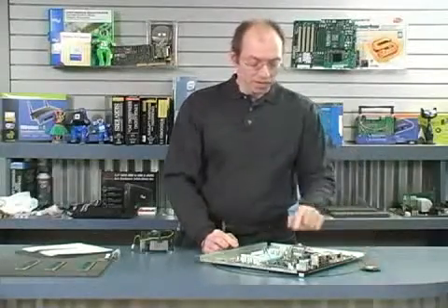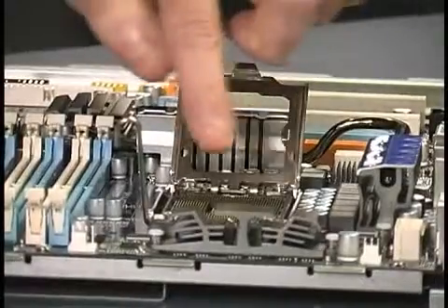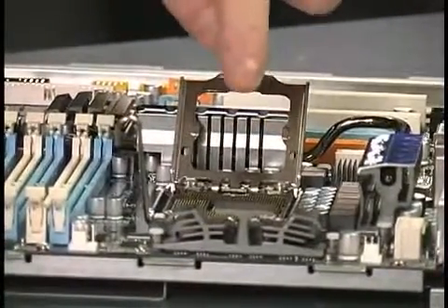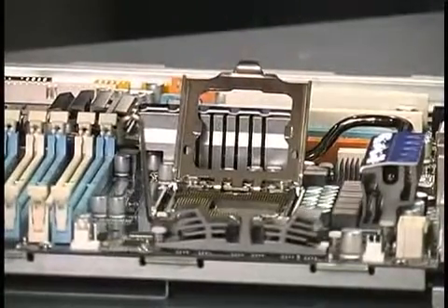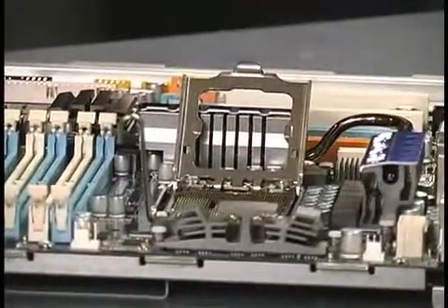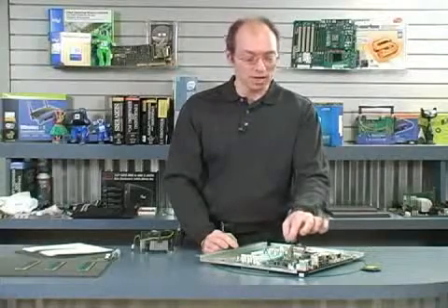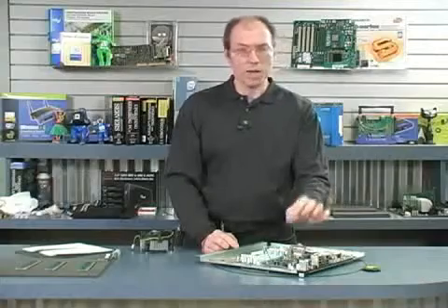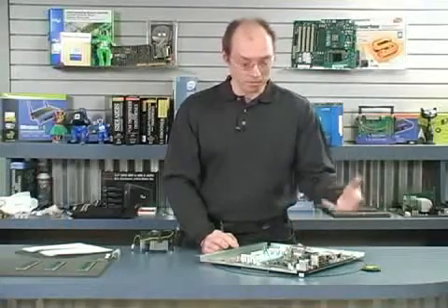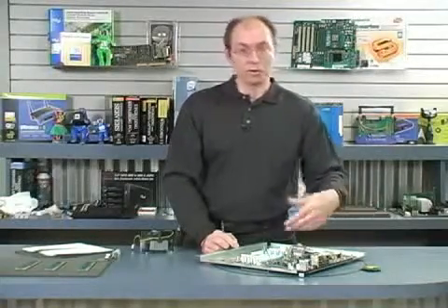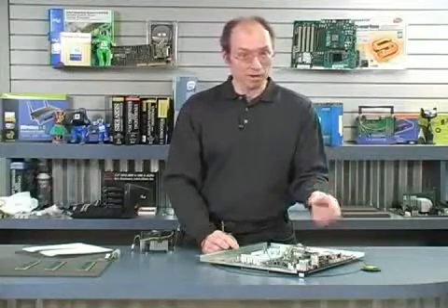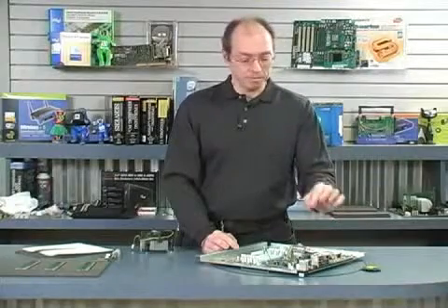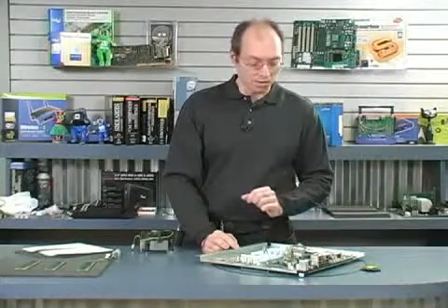This protector protects all the tiny little pins which are in the socket. There are, as I said before, 1,366 fine, very tiny pins in the socket, and you do not want to touch them. Just the slightest touch, snagging it with a little bit of cloth, something like that, will bend those pins and basically render the motherboard destroyed. And when you go to turn it in for a warranty repair, they will look at that. And if they see that the pins were bent, you may have a problem collecting on that warranty.